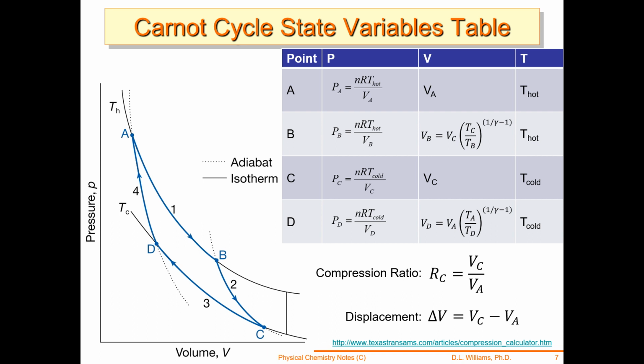All right. So let's go back to this, focus on why we need those adiabatic relationships. Remember, we might have something like the displacement or compression ratio given to us in the engine specs. And so if we start with these things down here, the compression ratio is VC over VA. So it's the largest volume over the smallest volume. And you can get the compression ratio higher if you make the smallest volume really small.